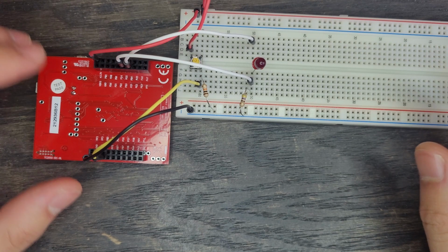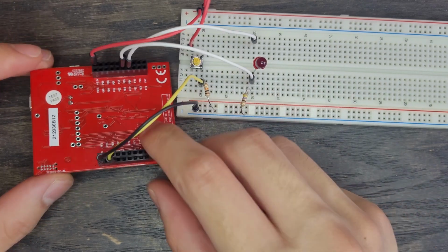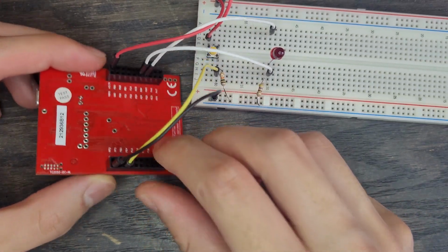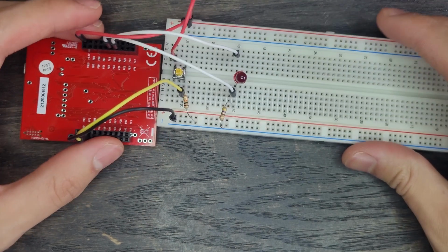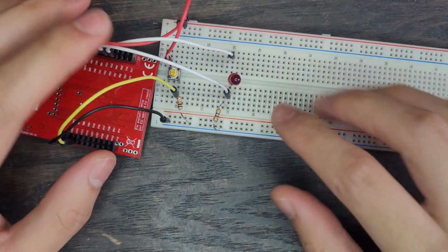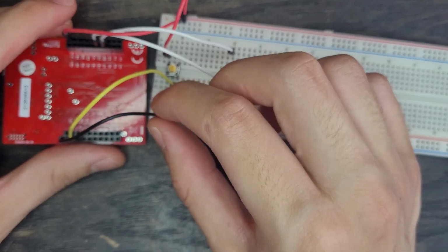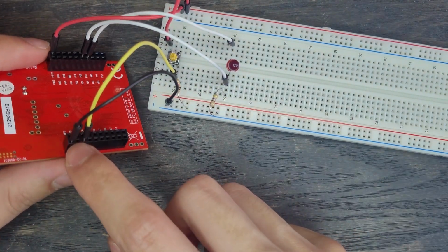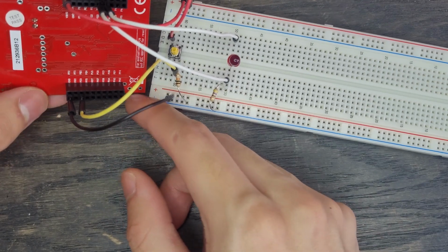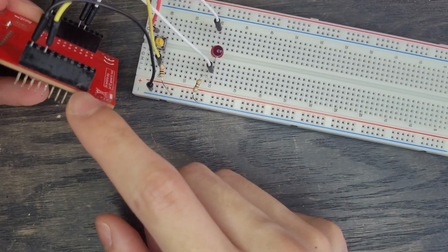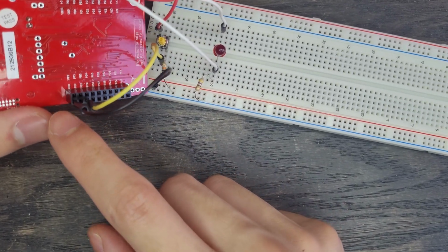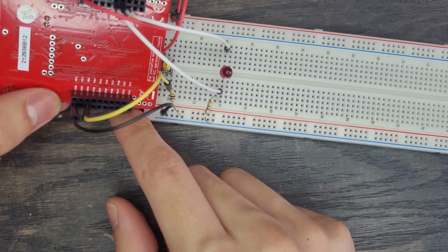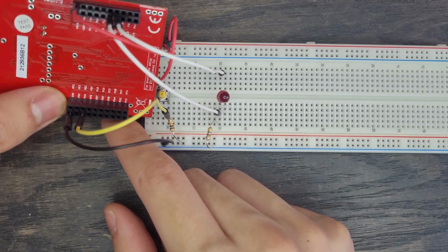So right here I have my board and everything. Notice how it's unplugged. So now we're going to be putting all of this in. I already built this just to kind of demonstrate everything, but we're going to show how everything works. The first thing is that we're going to need a ground wire. So if you look at your board, this is the back of the board. On this black part right here, it'll have something that says GND, and that means ground.